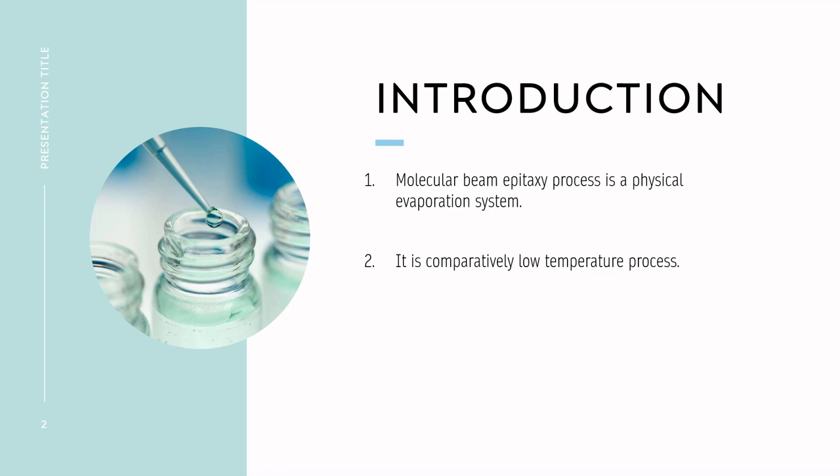Which layer? I mean the epitaxial layer. And vice versa. As well as its evaporation from the substrate and the reintroduction from the gas stream. Both these processes happen at higher temperature. So if I can have a low temperature process, that will be minimized. Then I can have less of an auto doping problem. So by using the molecular beam epitaxy process, we can easily minimize the effect of auto doping.